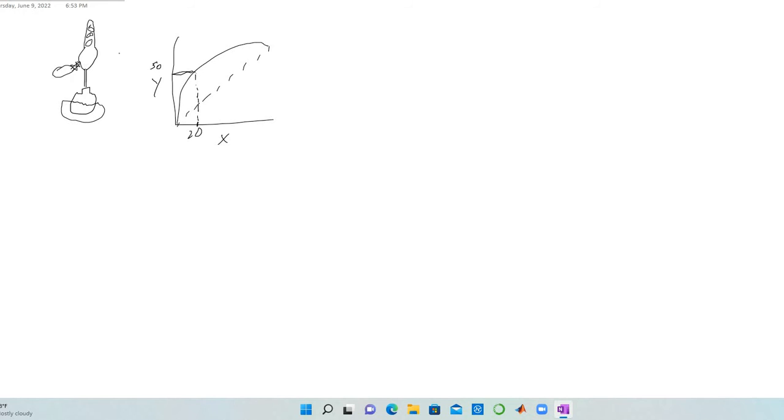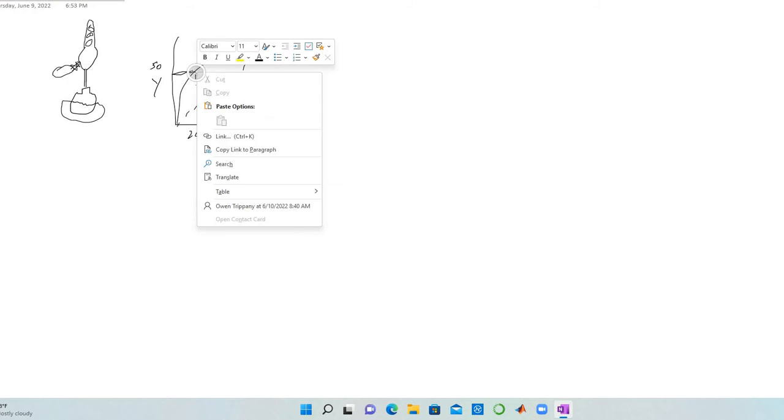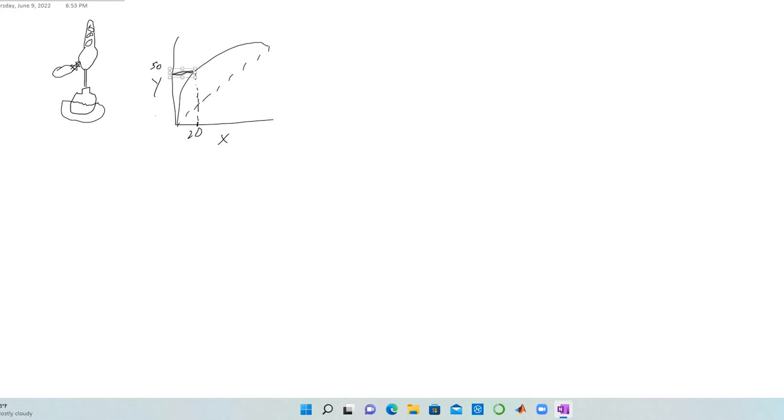All right, so what if we collected a lot of that and we did it again? Well, that means we'll go on the VLE diagram, we'll go across to the 45-degree line, because that's where Y is going to be the same as X. And remember, we just condensed this liquid, and we're going to flash it again. So this X is at approximately 50%. I know this is not to scale.